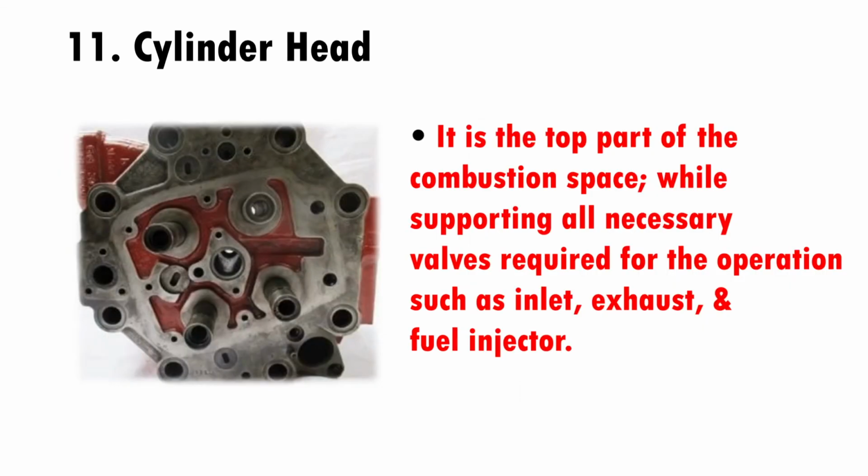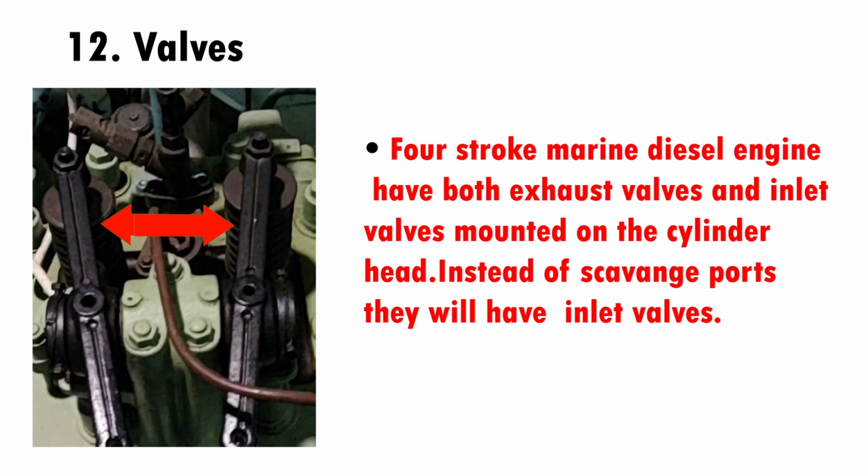Cylinder head. It is the top part of the combustion space, while supporting all necessary valves required for the operation, such as inlet, exhaust, and fuel injector. Valves. A 4-stroke marine diesel engine has both exhaust valves and inlet valves mounted on the cylinder head. Instead of scavenge ports they will have inlet valves.